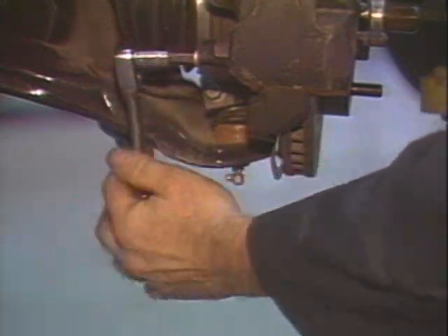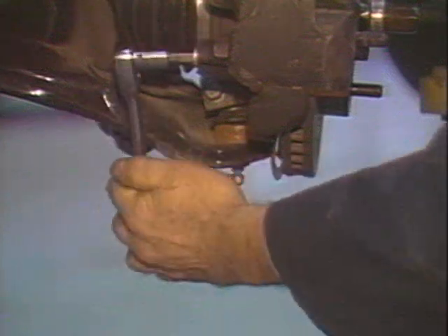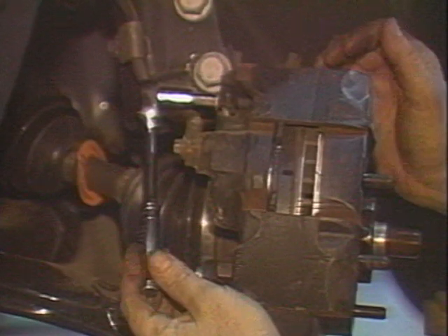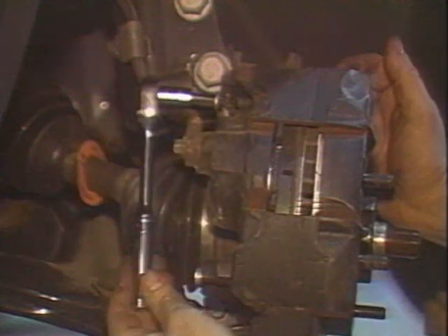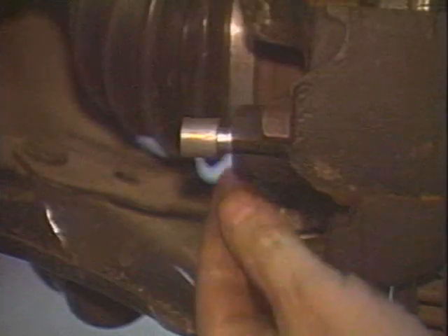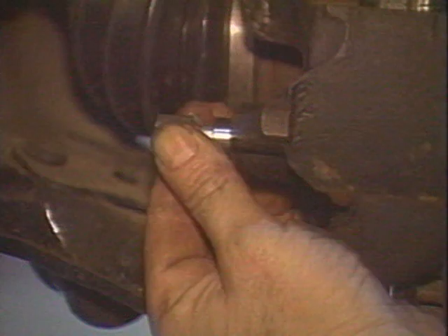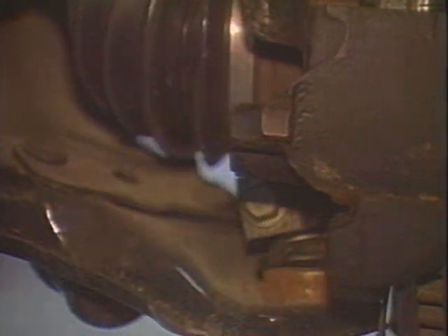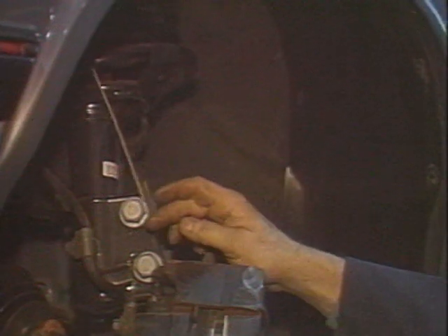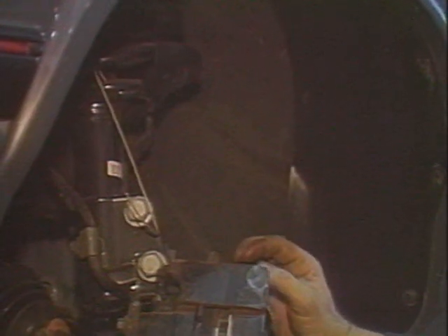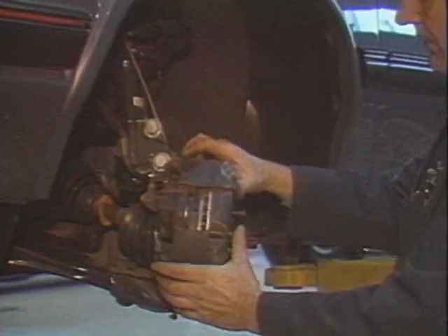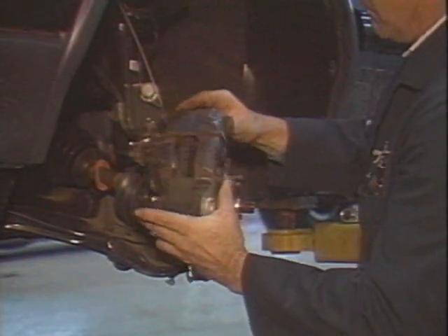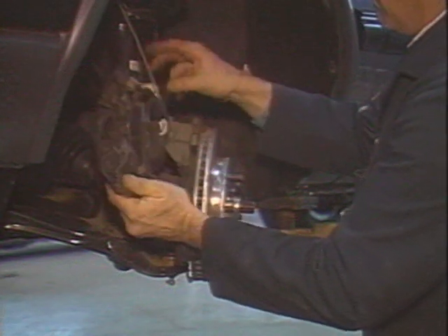Next, unscrew and remove the special bolts that hold the calipers onto their knuckles. Normally, 2 bolts hold each caliper. If rusted, use emery cloth to polish these special bolts. If the calipers are not going to be replaced or rebuilt, use heavy wire to hang the calipers up and out of the way. This will prevent damage to the brake hoses. Lift off and mount the caliper on these hooks if needed.